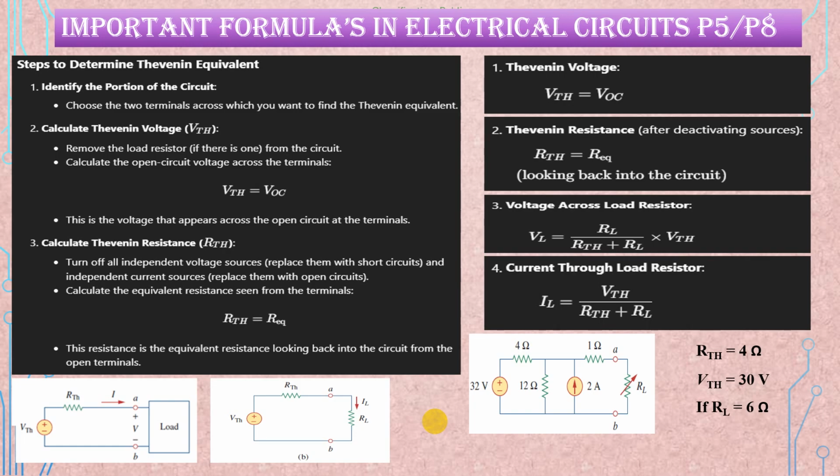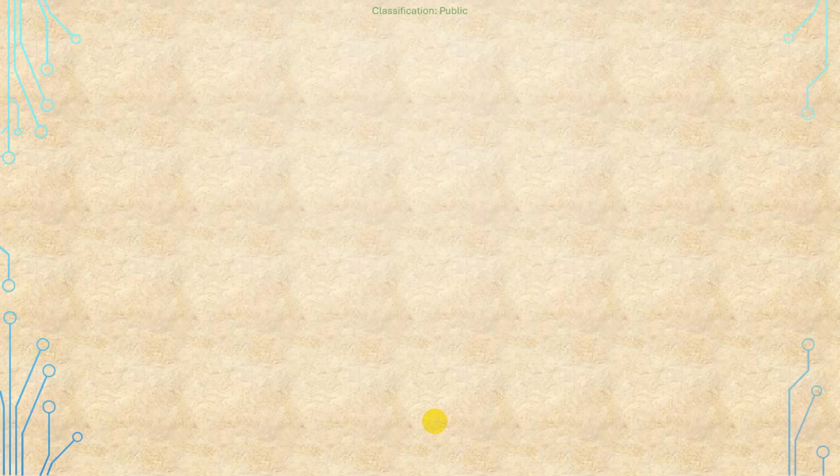Check the voltage across these two terminals, the open circuit terminals. What is the voltage? Put the mesh analysis, put the node analysis, then find the voltage across these two terminals. That is the VThevenin. Generally they won't give that big a circuit; small questions they will give. We will see that. For Norton's, we have to short those open circuit terminals and find the current.